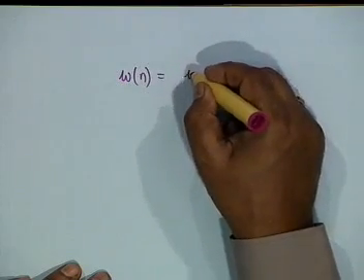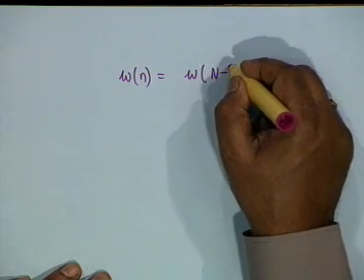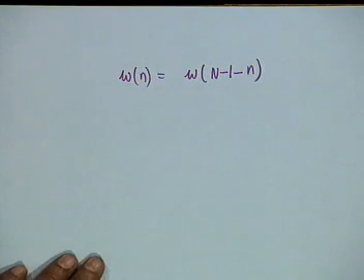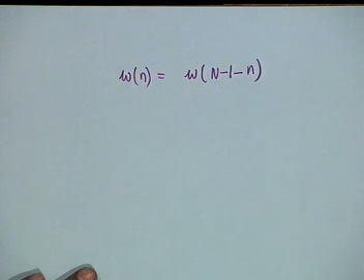So you have to write a separate program for the particular situation. We will not go into this, but you notice that in all these windows there is something that we took care of, that is Wn is a symmetrical window. Wn we had taken as equal to W of n minus 1 minus n. Why? Because of linear phase constraints.